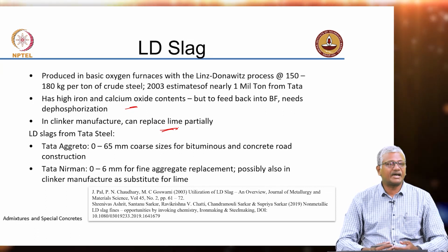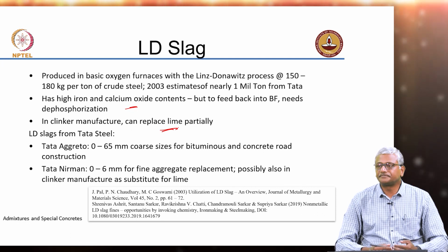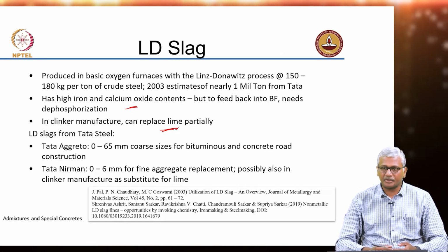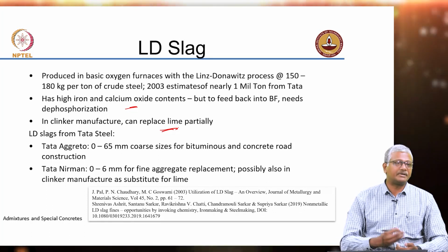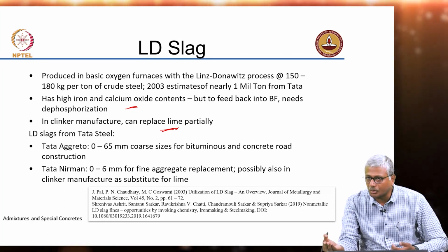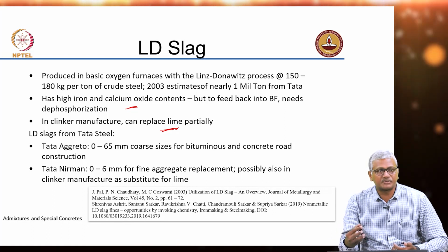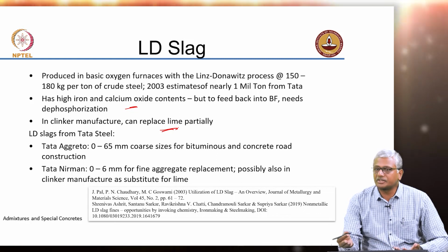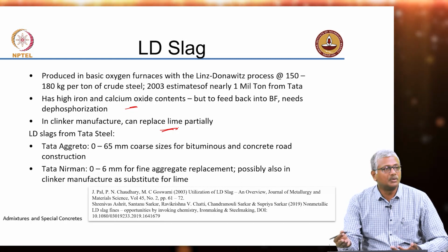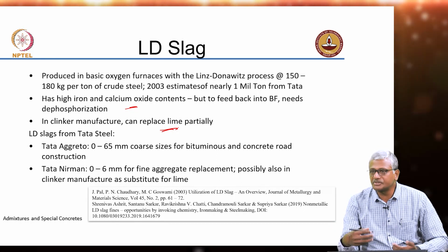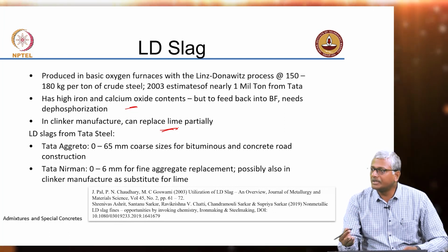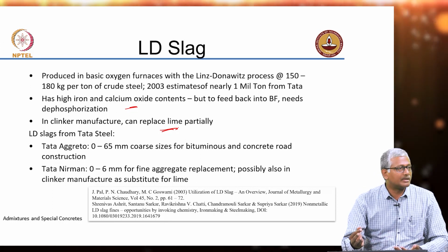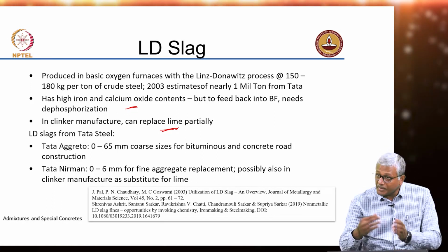What is the unsoundness reaction of free lime? Yeah, reaction with water to form calcium hydroxide. So, why don't we have that reaction even before putting this aggregate into concrete, convert as much of the calcium oxide to calcium hydroxide, which upon exposure to environment should convert to calcium carbonate. So, essentially what you are trying to do is mineralize the free lime that is present into a phase that is not going to be affecting the properties of the concrete which is made with the aggregate.